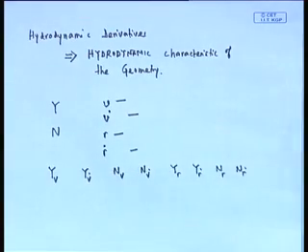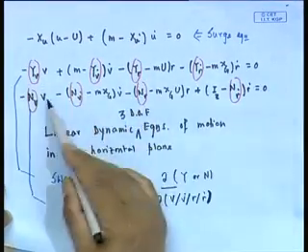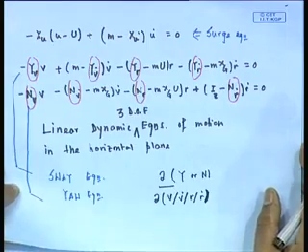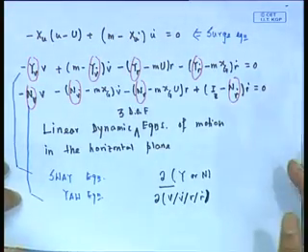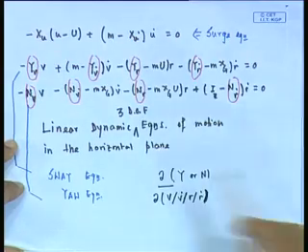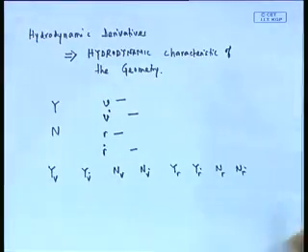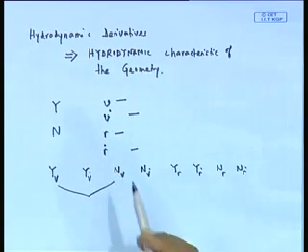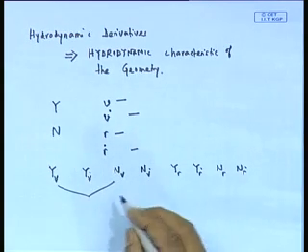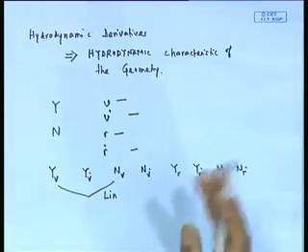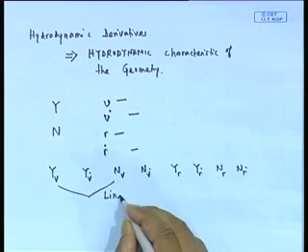If you look at this first, you will see there are 8 there, 1 2 3 4 5 6 7 8, very important 8 derivatives. That is obvious, because I am talking of 2 motions, forces Y and N, and 4 velocities. So, 2 into 4 gives you 8, of which, just for definition purpose, these 2 are linear velocity derivatives. Linear because V is straight line velocity and R is rotational velocity.